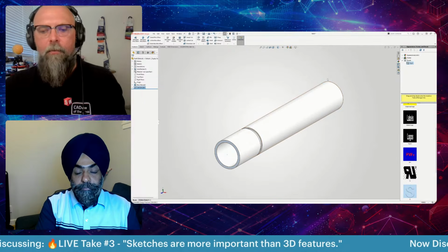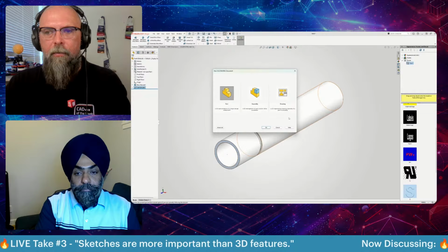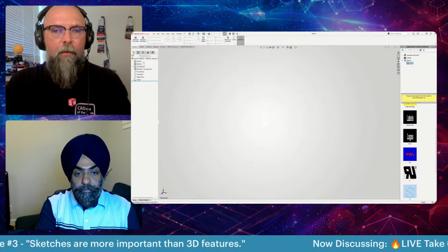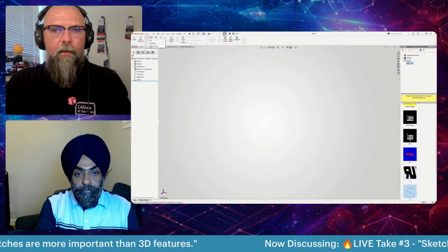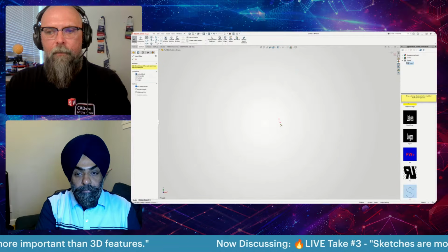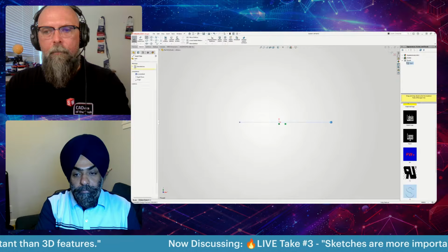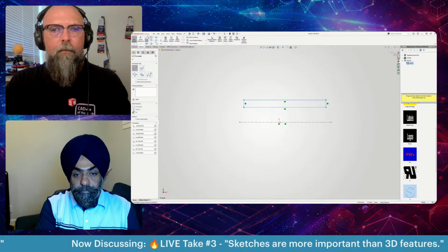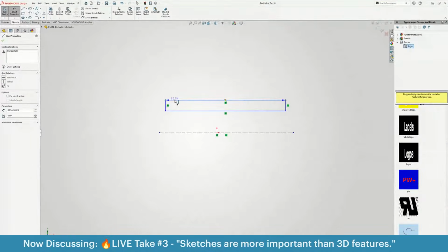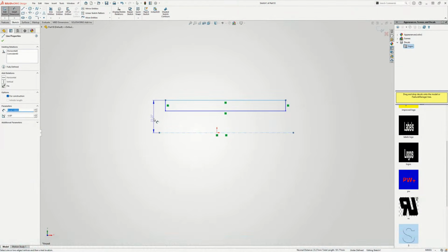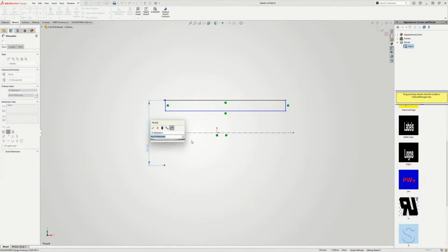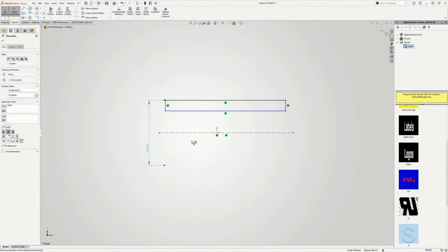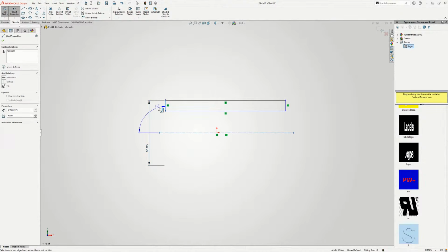Okay. So we're just going to create a new one. I think. There we go. So for this sketch, I'm going to be using a center line. Perfect. And then we said it was. So the great thing with the center line is that if I click here, since I want the diameter of the tube, I can just move down here, and then I can say the complete dimension, which was 50. And this one was 4.